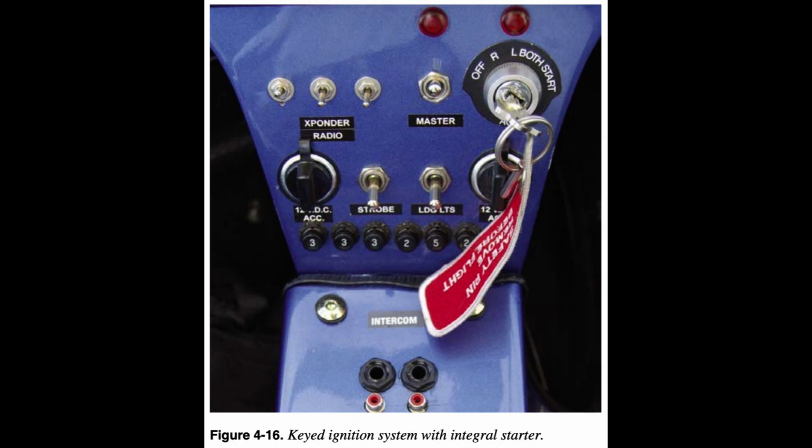The aircraft electrical system can fail, the battery can go dead. However, this has no effect on the ignition system. The electricity from the ignition magneto/generator goes into the ignition control box where the correct voltage is produced in time to fire the spark plugs at the proper time. Modern WSC aircraft use an electronic capacitance discharge system that operates without any moving parts to increase reliability and efficiency. Capacitance digital systems, CDI, operate similarly, but they have the ability to change the timing of the spark for different RPM. Consult the POH for the particular system for each engine.